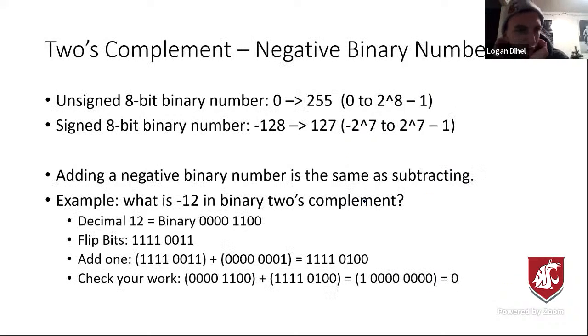So I'm going to move on to 2's complement. 2's complement is used for binary numbers. If you wanted to have negative binary numbers, then you need 2's complement or some other form and some custom circuits. But we always use 2's complement in like 100% of the cases. Normally with an 8-bit binary number, we could go 0 to 255.